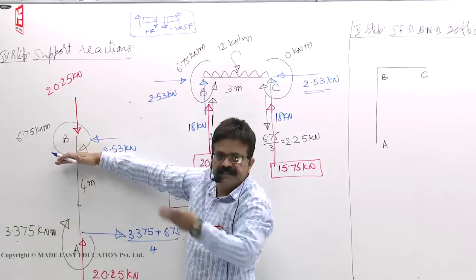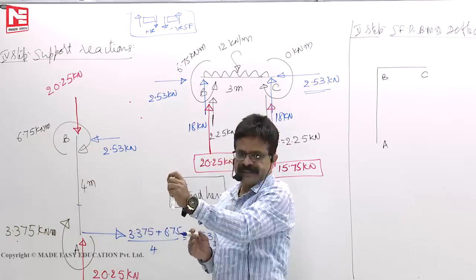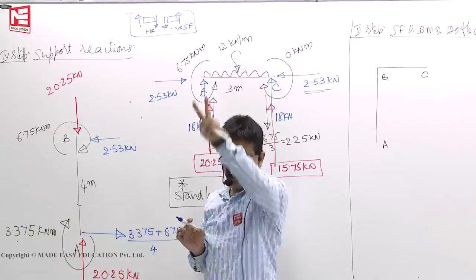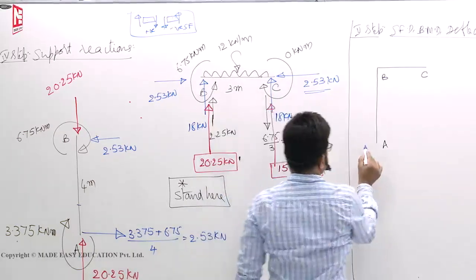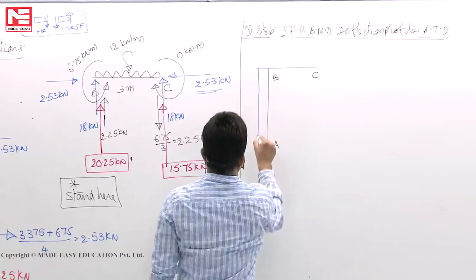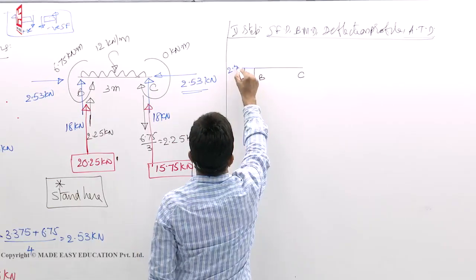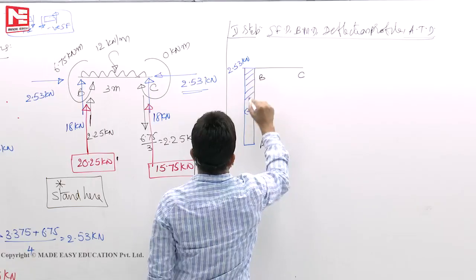Now stand here, section left side 2.53. Like that, at two sections you stand there, look one side. If same magnitude is there, it means that shear force is a rectangle because it's not changing. 2.53 negative. This is minus. Once you show this minus value,